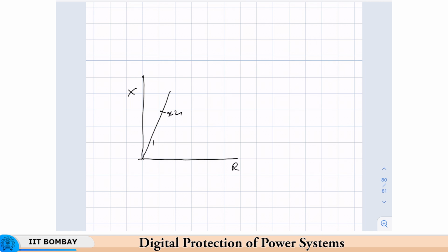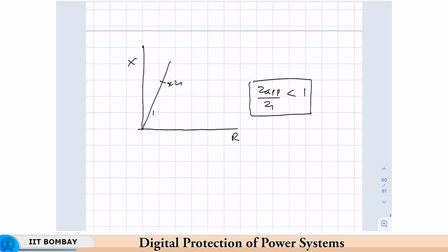But even before that, what we have done here is, we have ignored the fault resistance, if there is any. Okay, and in practical systems, you could have some impedance coming in the path of the fault. That means the fault will have some impedance, and the locus may not lie on the transmission line itself.